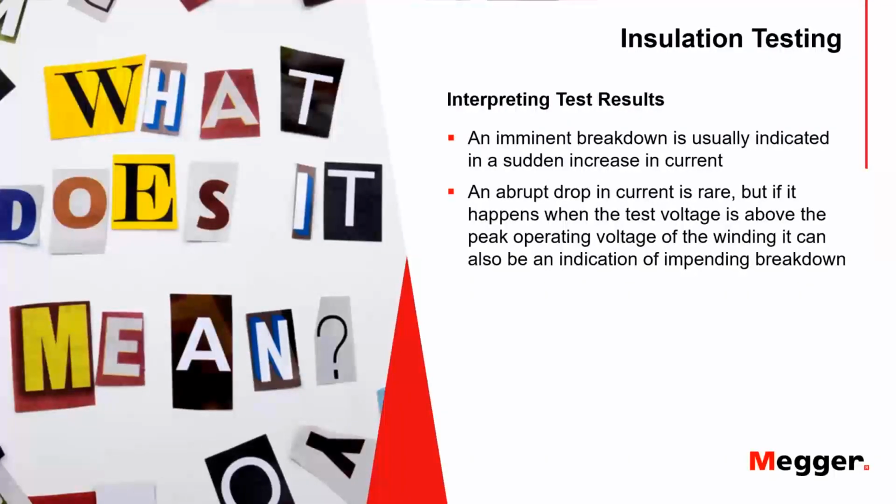And you can also watch the voltage and progress of the test on the display, because it will show you the line creeping up, and you can actually do something similar to a tip-up test, where what you're basically looking at is that the current should follow your voltage. If it doesn't, the current will start to creep up higher than the commensurate voltage, starting to deviate from what you would expect from Ohm's law. So let's look at the next slide.